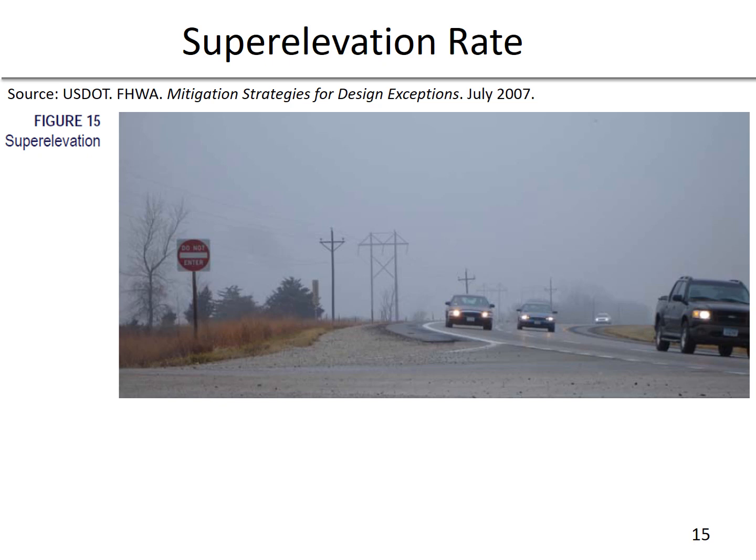And typically, if you're in an area that has snow and ice as a common feature on the roadways, 8% will typically be a maximum superelevation rate. And driveways and intersections require a low superelevation, typically 4% or 6%, depending on the location.